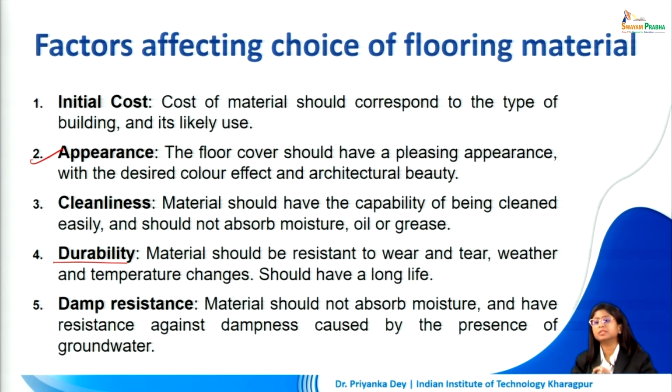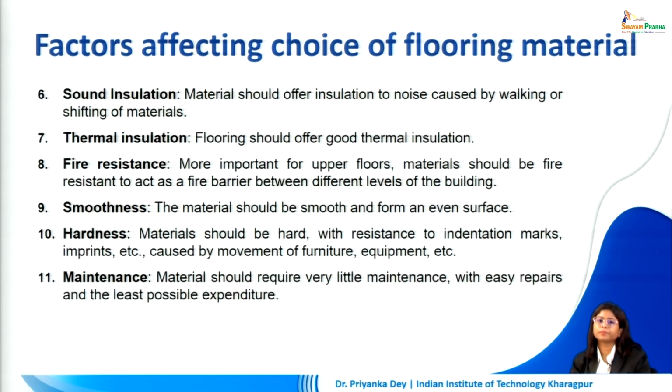Damp resistance, especially if you are dealing with ground floor or basement floors, the material should be such that it does not absorb moisture very easily and it has resistance against dampness which is caused due to the presence of groundwater. So that is also something we need to keep in mind.